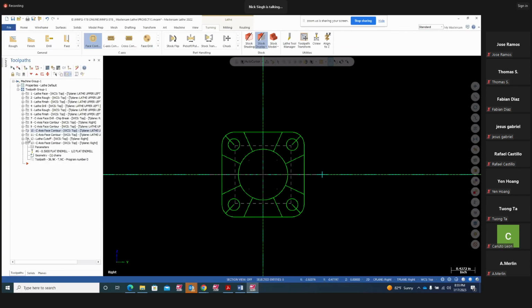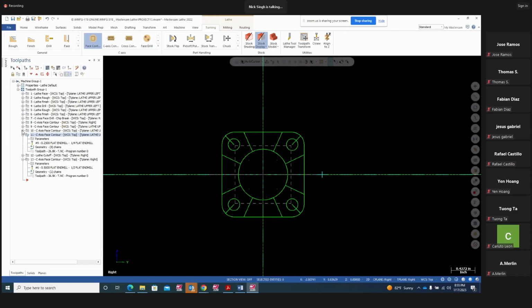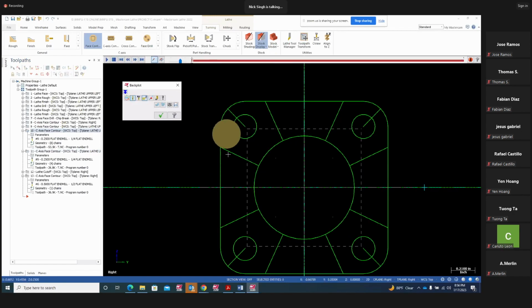So for this, we are using a quarter-inch flat end mill, and let me show you the toolpath. Then we're going to go over the program. So here, this is how it's going to do. It's going to cut the inside slot right there, with the flat end mill. It's going to cut this one here first. We are using this geometry, cutter comp to the left in this direction. And then we're going to use this geometry, then this, then this.